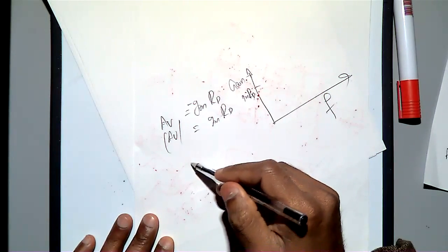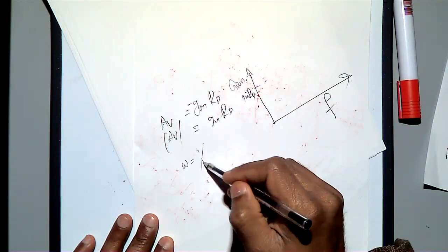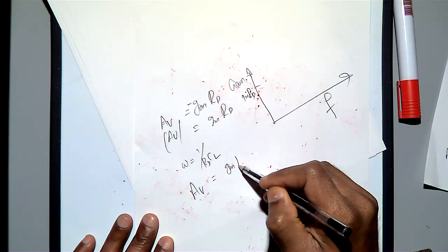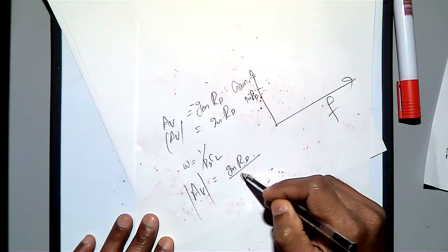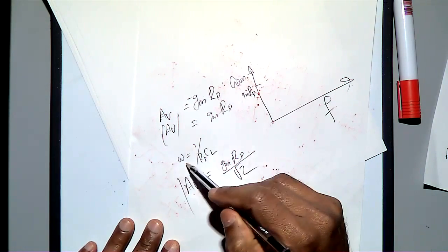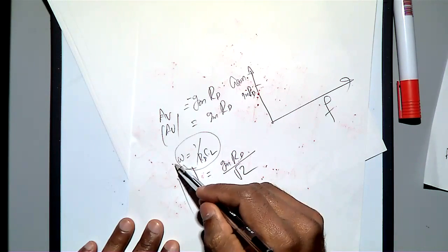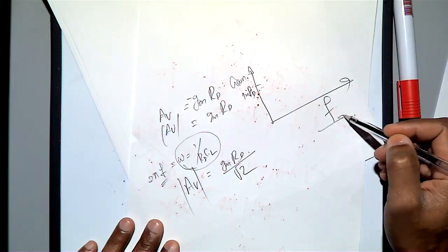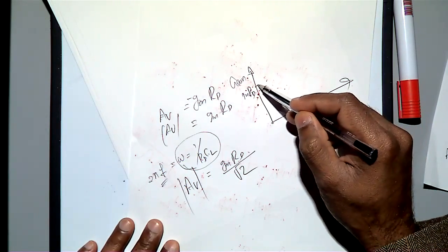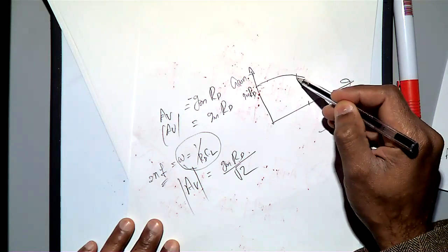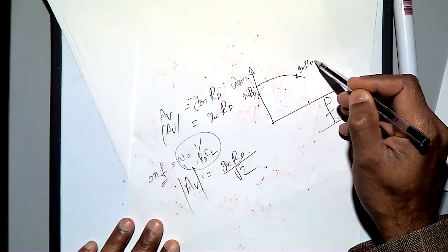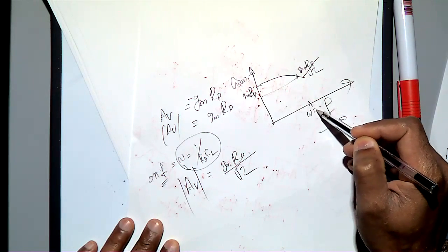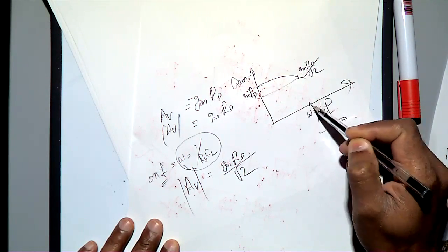But from the transfer function, at omega equal to 1 by RD into CL, your gain is equal to gm into RD divided by root 2. At this point, omega equal to 1 by RD CL, and omega equal to 2 pi f, so this is the corresponding frequency. Maybe that is this point, so the response comes down like this. Gm RD by root 2 is your new value at omega equal to 1 by RD into CL. You know what I meant?